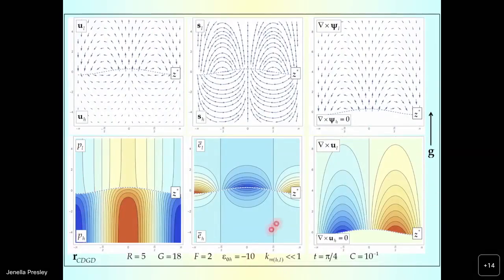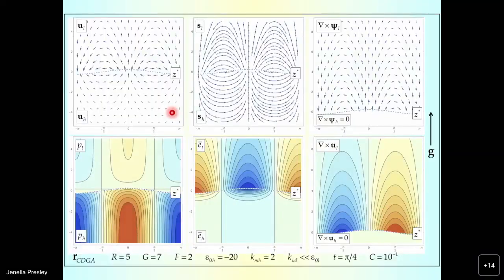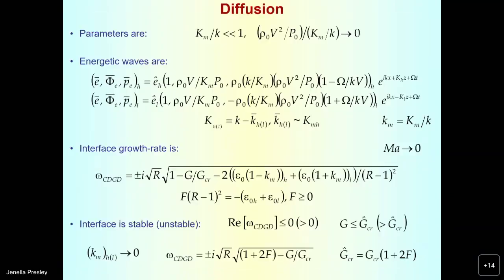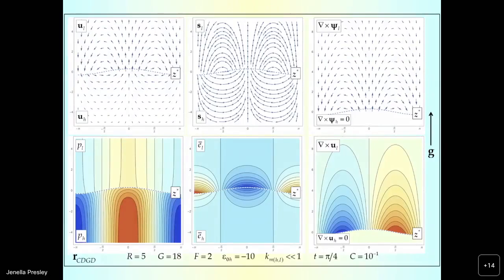We have a completely different picture for the energy perturbations, because when we had advection, it was a strong anisotropy. Essentially, for the advection, the energy perturbations were attached to the interface on the side of one fluid, and they were going very far away on the side of the other fluid. Here we have a symmetric distribution, essentially, with small perturbations on both sides. And again, there is some correlation between these energy perturbations and the vertical field, which is being formed in the bulk.